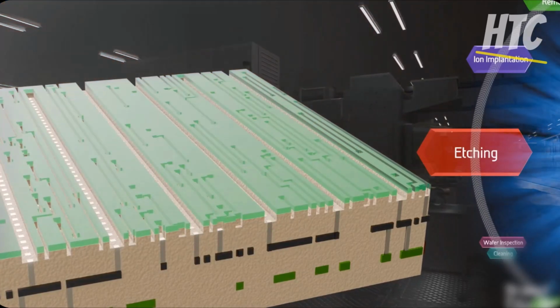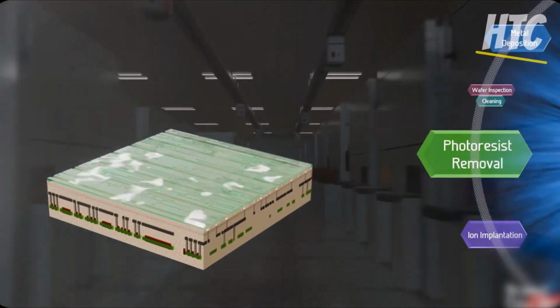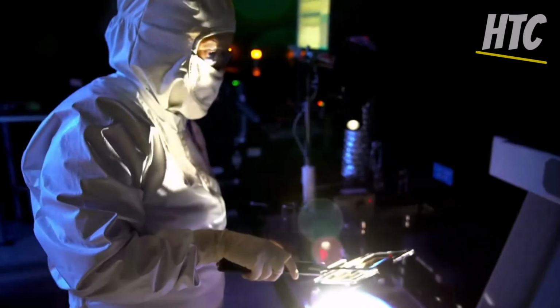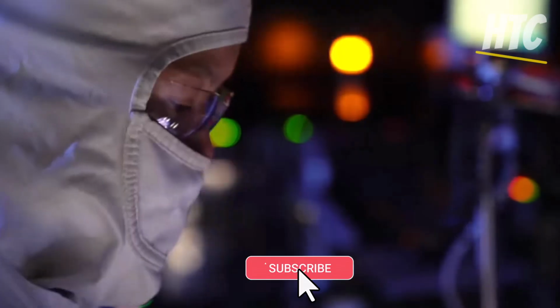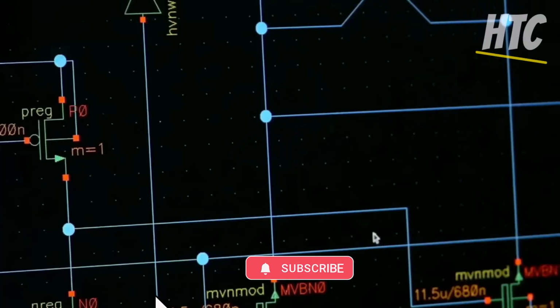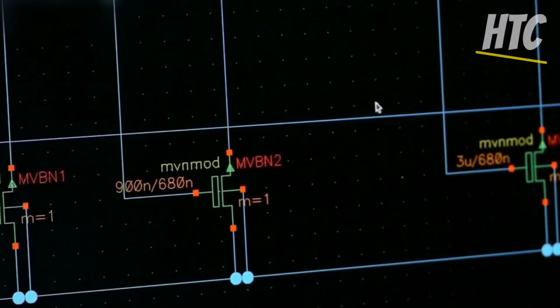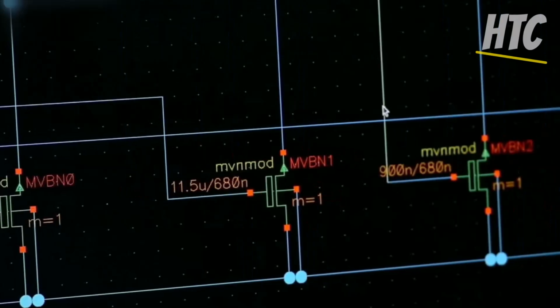Critical to this process is chemical mechanical polishing (CMP), which levels the surface between layers, ensuring that subsequent depositions occur on a uniform base. Manufacturers also integrate yield enhancement techniques and redundancy checks during this stage to maximize the number of fully functional chips per wafer.